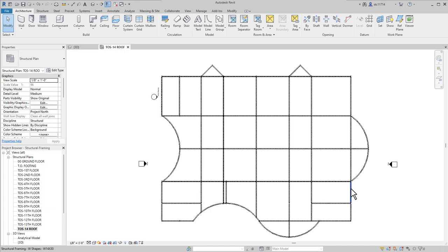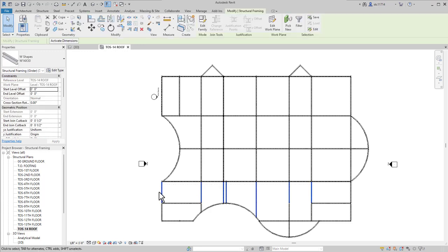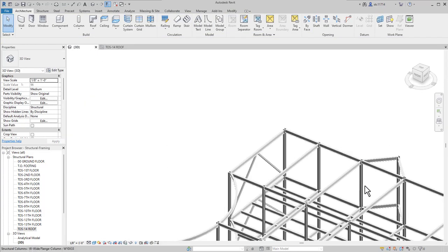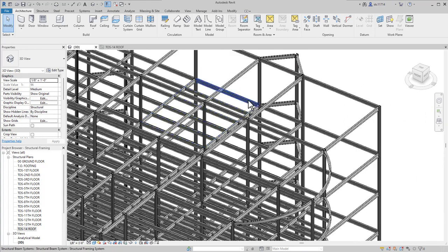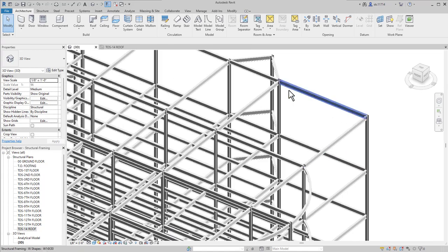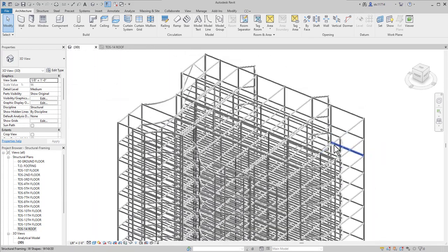Again, in this lower section here, these bays are not going to have the beam systems, so I can come in a little bit and select these. And looks like I would also need to add a few more below. Unfortunately, it looks like I'm able to enter in those values. Again, if I take a look at this in 3D, then all the ones running north and south should be down 2.5 inches, except for the ones on the end, because again, we are not going to be working with those bays there.